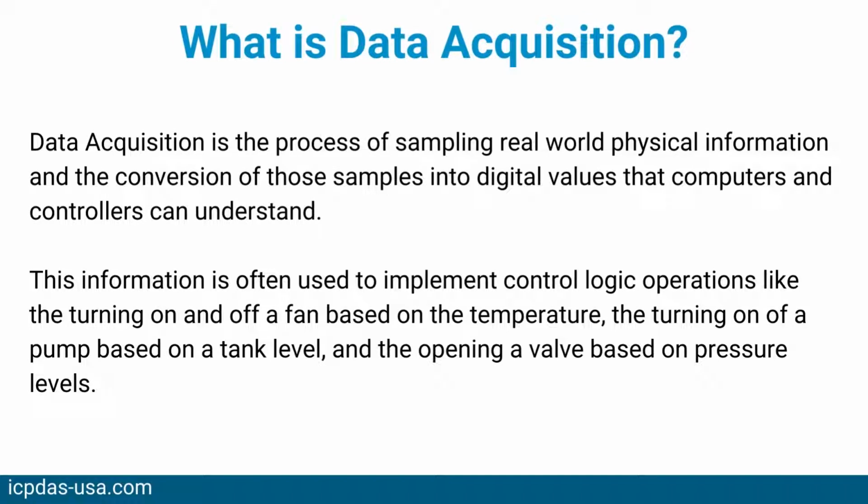Data acquisition is the process of sampling real-world physical information and the conversion of those samples into digital values that computers and controllers can understand. This information is often used to implement control logic operations, like the turning on and off of a fan based on the temperature, the turning on of a pump based on tank level, and the opening of a valve based